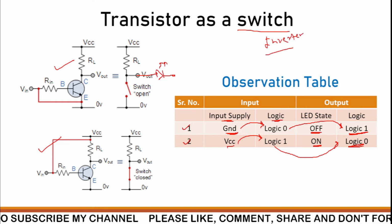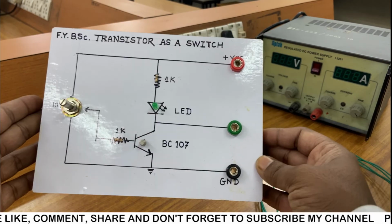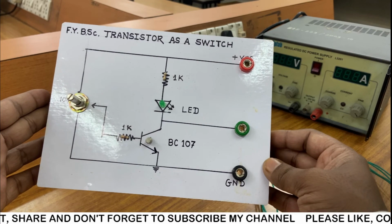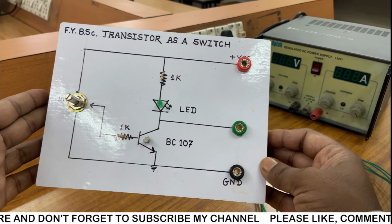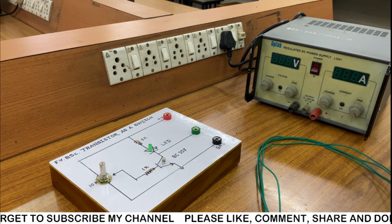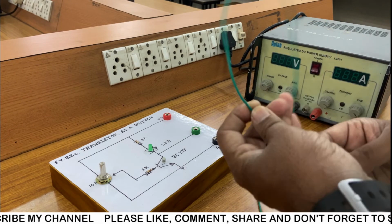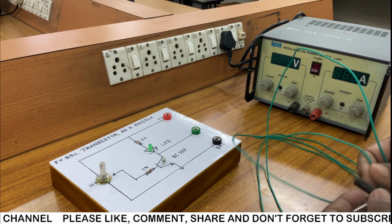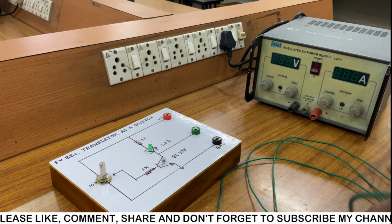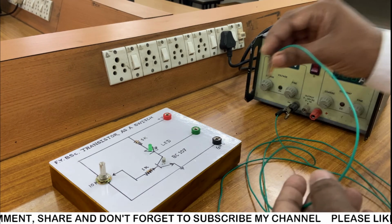Let's look at how we do the practical in the lab. This is a transistor as a switch circuit. We have a variable potentiometer at the base terminal, an LED, and a BC107 common emitter transistor. How are we going to connect it? We need to set the regulated DC voltage to 5 volt, and this 5 volt should be given to the VCC of the transistor as a switch socket, and ground should be connected to the ground.